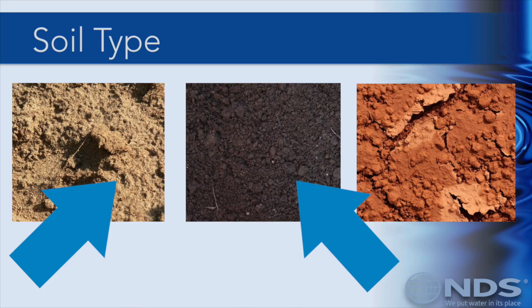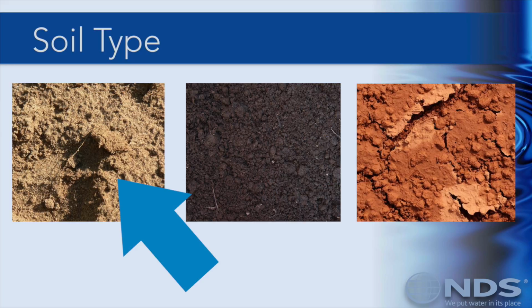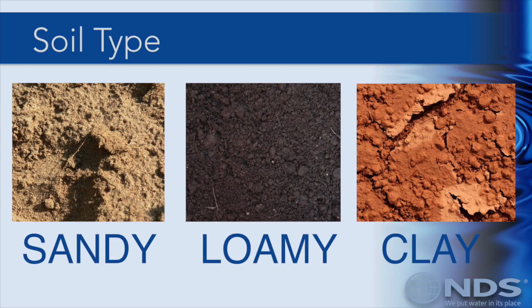Certain soils are more porous, so they can absorb more continuous rainfall before water begins to puddle on the surface or run off. Clay soil has the lowest infiltration rate, and sandy soil has the highest. You will want to test the soil in several areas of the landscape to find out what type of soil is present. This is important because you will need to know this as a key factor in sizing and placing drainage components. Here's how to do a simple soil analysis.